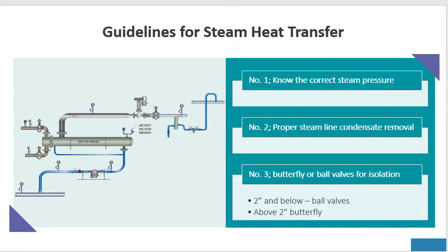And the other thing is we utilize butterfly or ball valves for isolation. 2-inch and below, ball valves. You know, the technology has accelerated in the last 15 years on ball valves. Above 2-inch, butterfly valves, same thing. Technology in butterfly valves has accelerated in the last 15 years.